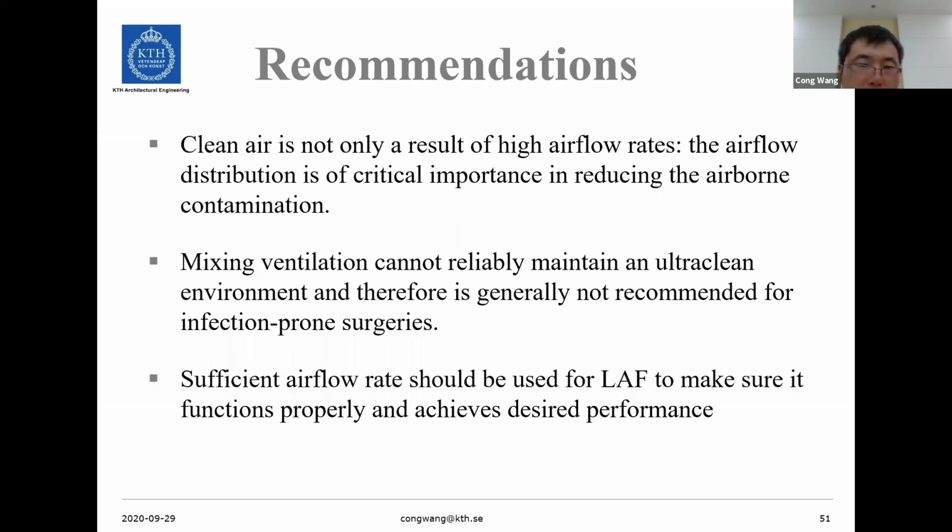And then sufficient airflow rate should be used for laminar airflow ventilation to make sure it functions properly and achieves the desired performance. If we recall the study, we first investigated the laminar airflow ventilation at 100 ACH, which is the desired airflow rate. But when we decreased the airflow rate to 60 or 40 ACH, the laminar airflow ventilation did not fulfill the ultra clean air requirements.